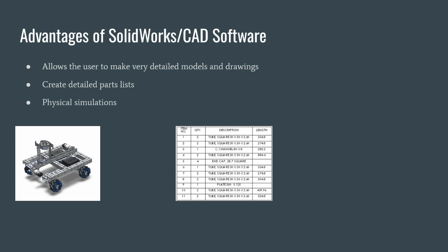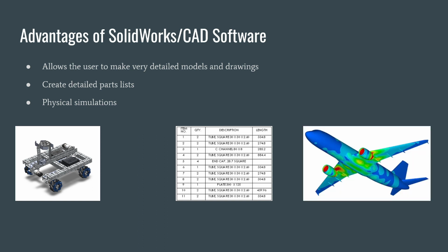Lastly, this one is a bit technical, but some CAD software, especially SolidWorks, allow you to do partial or even full mechanical simulations of the robot's functions. If you're willing to invest enough time, you can use SolidWorks to simulate the rotation of motors, the interaction between multiple objects, and do finite element analysis to make sure your design holds up to stress well, and make improvements if it doesn't. Mechanical simulations essentially allow you to test a prototype without spending the time to build it, and then realize the mechanical failure after it's already been built.